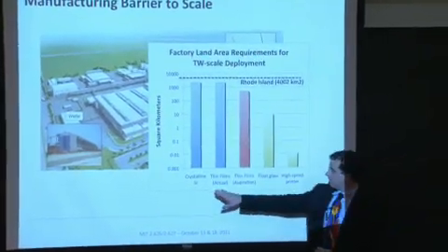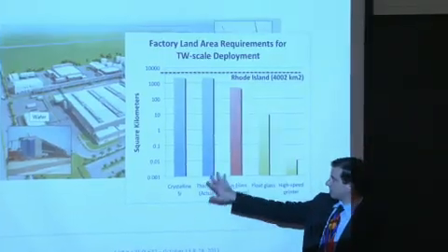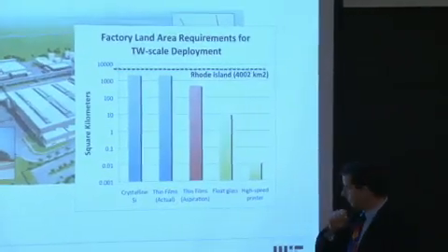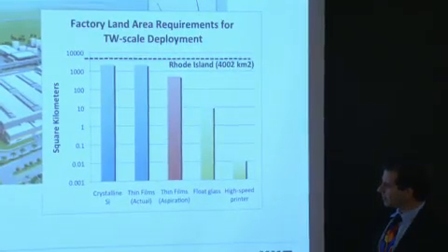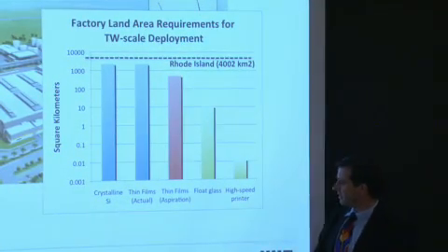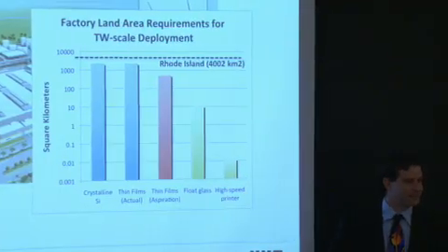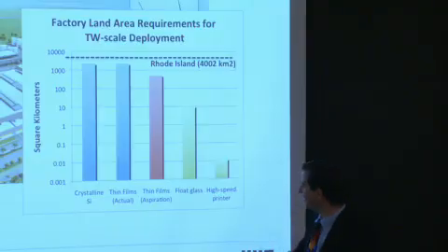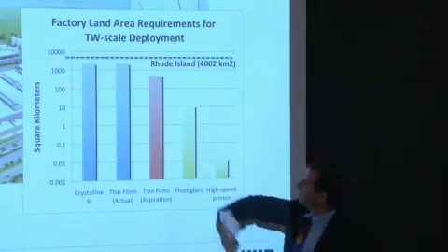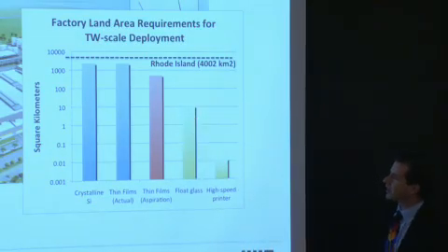So instead of using thin film or crystalline technologies that are currently being used today, if we used, let's say, a float glass-like process, so these would be extruded pieces of silicon on some bed of, I don't know, liquid tin would be for float glass, some equivalent for silicon, you could reduce the area by about 2 orders of magnitude.